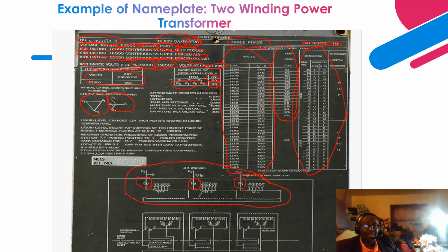And I made mention that the de-energized tap changer, which is plus or minus 2.5% above and below, providing a total of 5 tap positions, is located on the high side. So this allows you to vary the taps on the high voltage side to achieve the variable voltages you need, to maintain the required input voltages to achieve the required output voltages that are meant for the load.